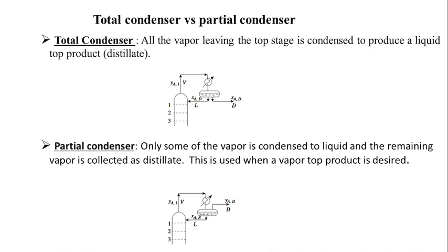On the other hand, if you have too little space for your downcomer, through which the liquid has to travel by gravity to the next tray, the downcomer liquid backup may be so high that it may get flooded. So there is a balance.